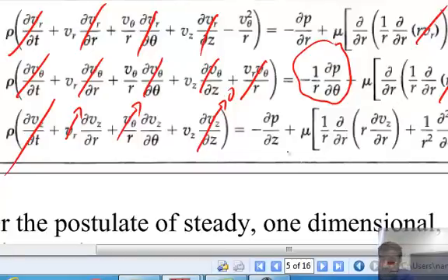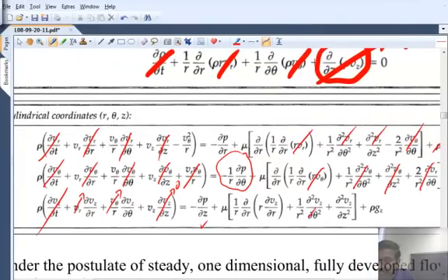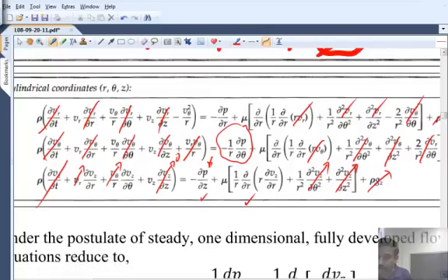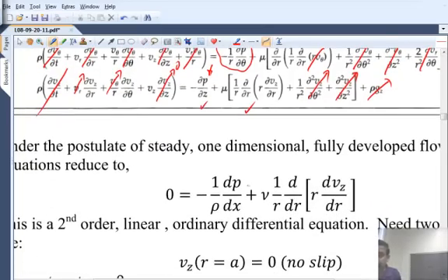Okay, so this is not going to be 0, and in the theta direction there is no variation, and in the z direction there is no variation, but there is a variation of the velocity in the r direction. So this term will survive. We can throw this term out because we are absorbing gravity into hydrostatic pressure variation. So the meaning of this pressure is whenever you drop G. So that equation then simplifies to minus 1 over rho